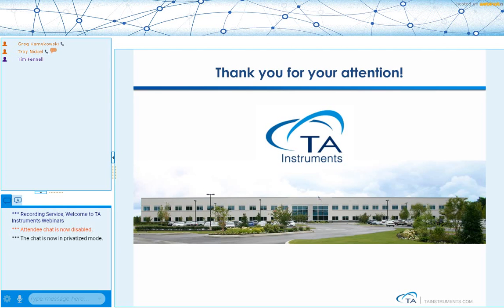I think with every test that we mentioned, I don't think any one of them uses more than probably more than 5 mils. So it's not all that much consumption of material to do tribology testing, or for that matter, just about any kind of rheology test. Especially like parallel plate and cone plate. Sometimes concentric cylinder might take over 20 mils, but that's on the high side. So, okay. For tribology, probably just a few mils will be more than enough.